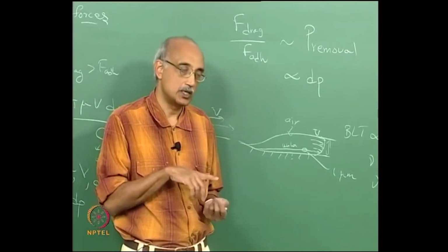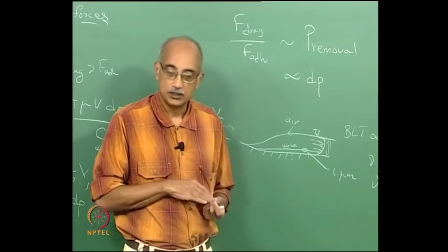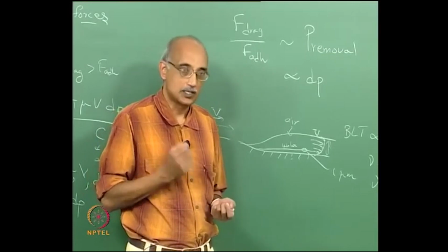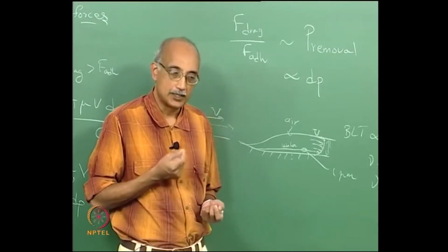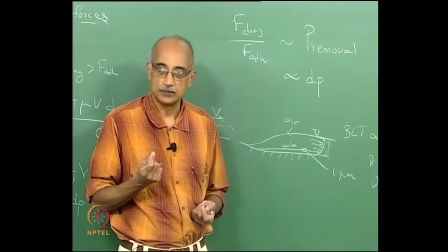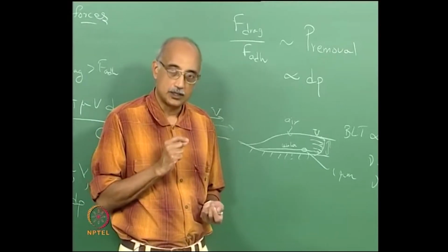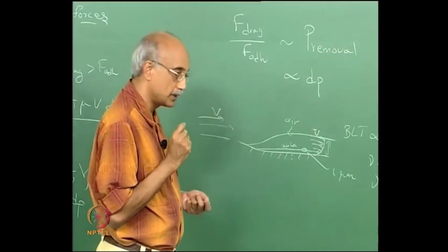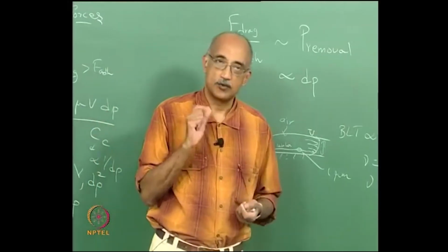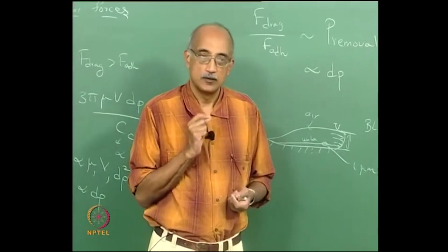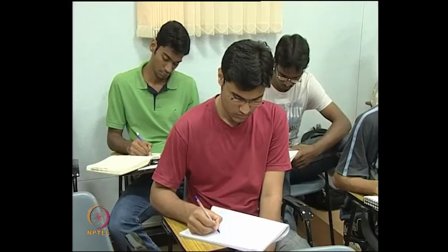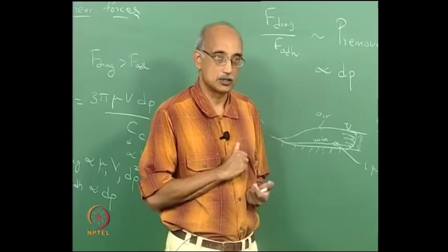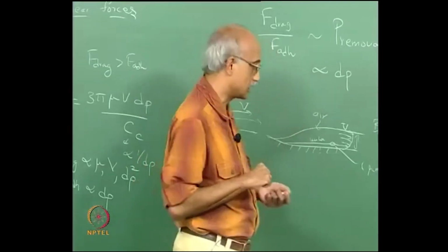And that brings us to the last cleaning method that is probably the most widely used in industry for removing submicron particles, and that is methods based on acoustic fields, particularly ultrasonic cleaning and megasonic cleaning. Now these techniques are particularly suited to removing even the finest particles from surfaces without causing excessive surface damage, provided they are properly controlled and optimized and so on. So we'll talk about these techniques in a little more detail.